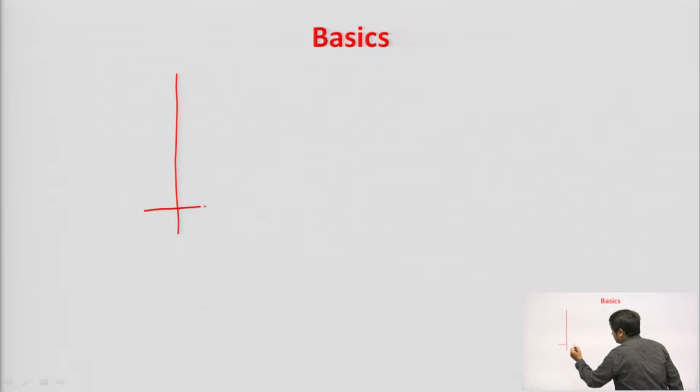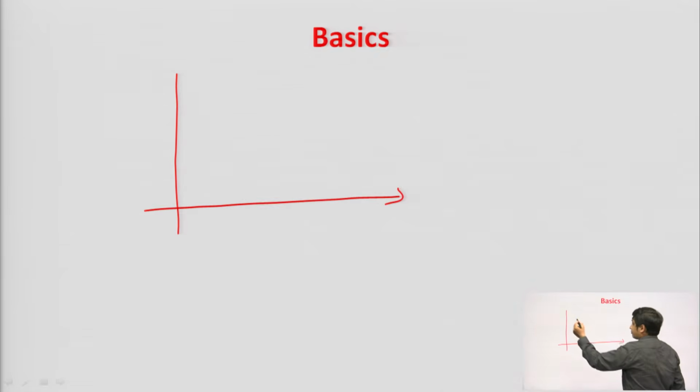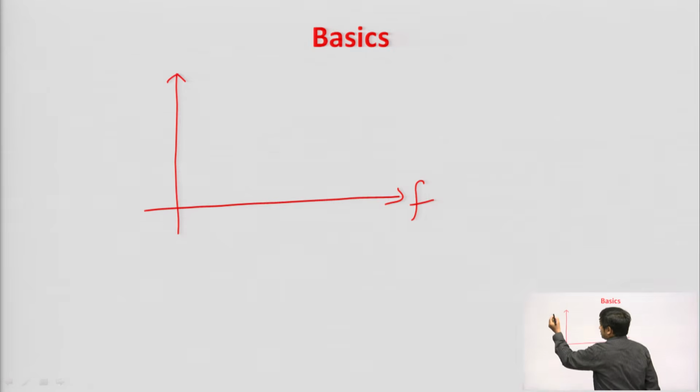So, when we draw the frequency response of the common source amplifier or common emitter amplifier, on the x axis there is frequency, and on the y axis there is the voltage gain in dB. In dB means 20 log of the magnitude of V naught upon Vin.